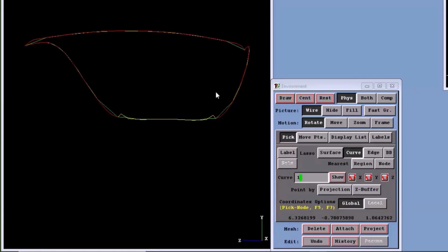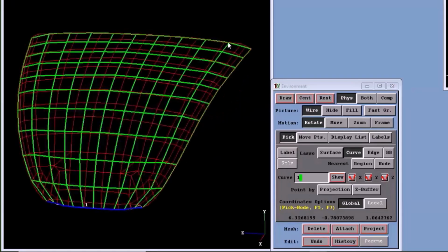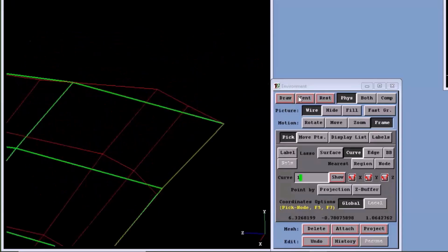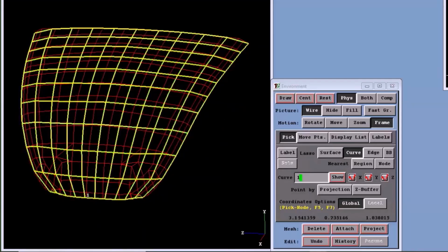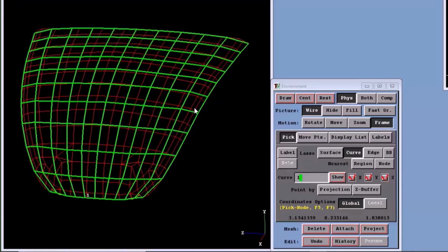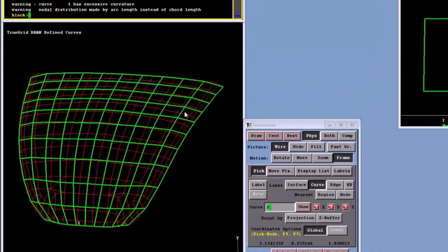It's not very good. For example, you'll notice here, well, why is that happening? Well, the features of this surface are smaller than our elements. And as a consequence, we're losing some of the detail. Well, that's one of the reasons why a single block doesn't work. You have to have more detail in your block structure to capture the features you want. And what I want to do is to be able to move this vertex right there, but it's not a partition. So I will make it a partition.